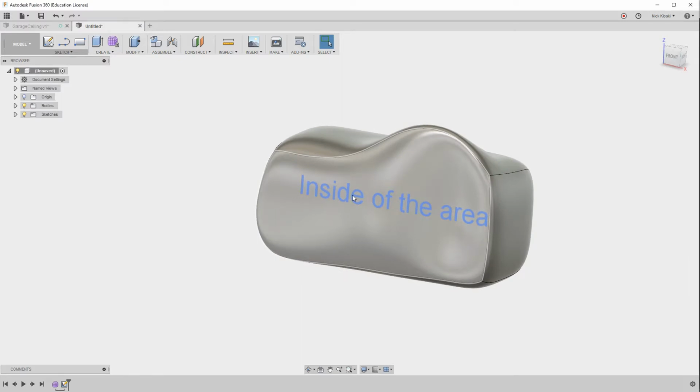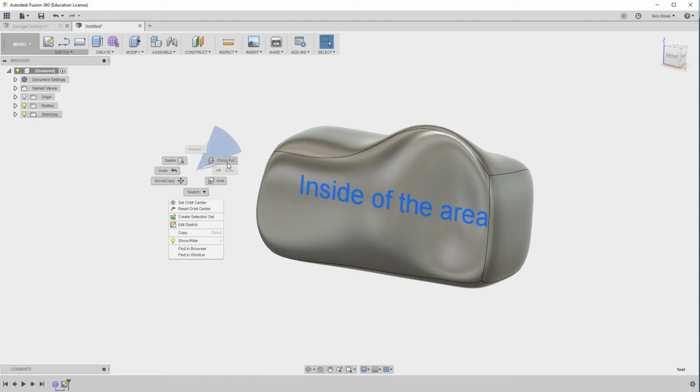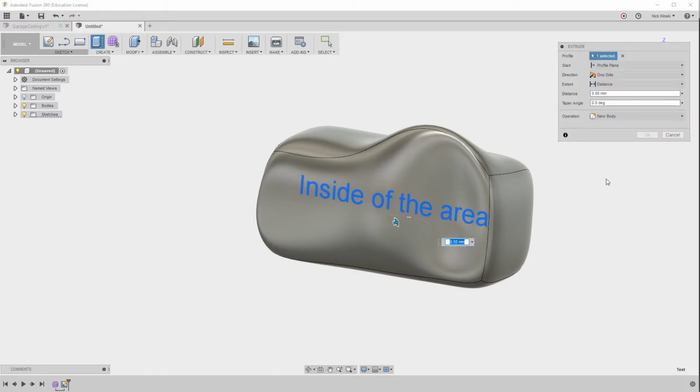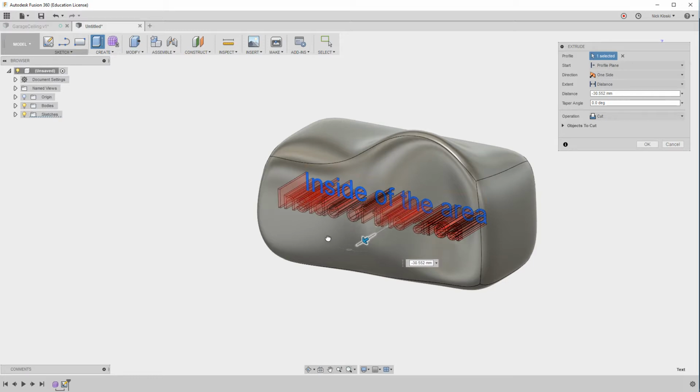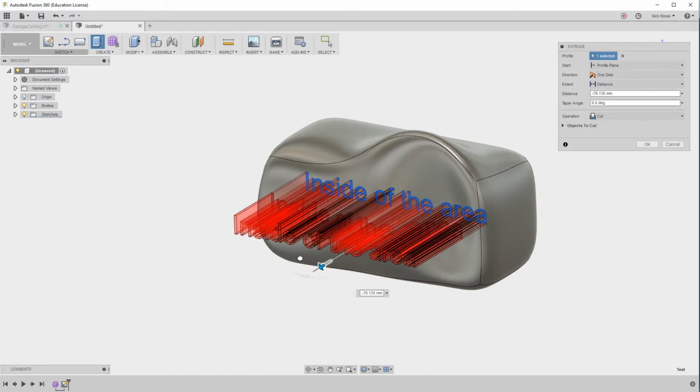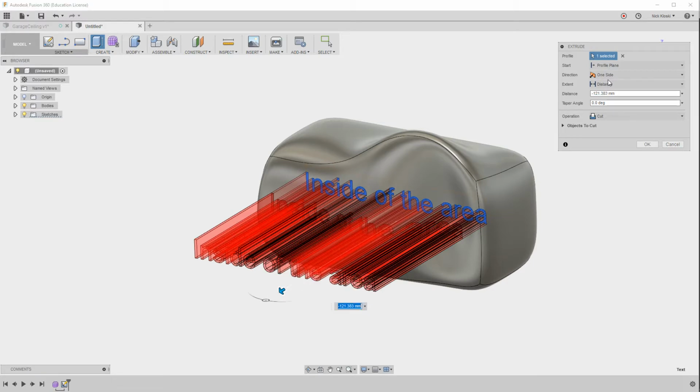But if I hold down my mouse button and then select text and then right click, you'd say press pull, but it actually starts the extrude tool. Now you can say a normal cut of the text. You don't have to explode it or anything, which is very nice. It's doing kind of cuts, so you could certainly cut that out. But the very nice thing now is,